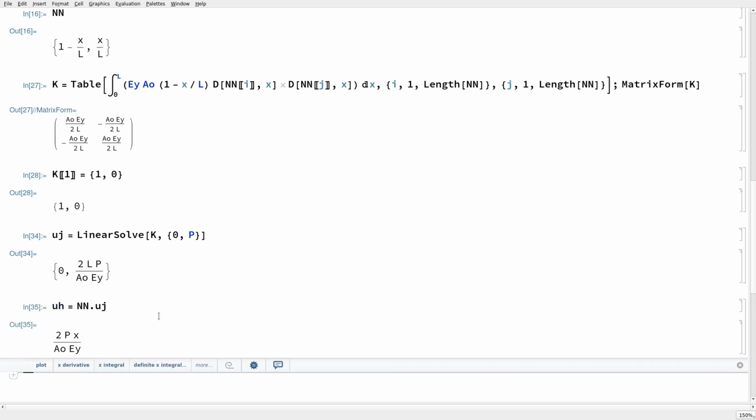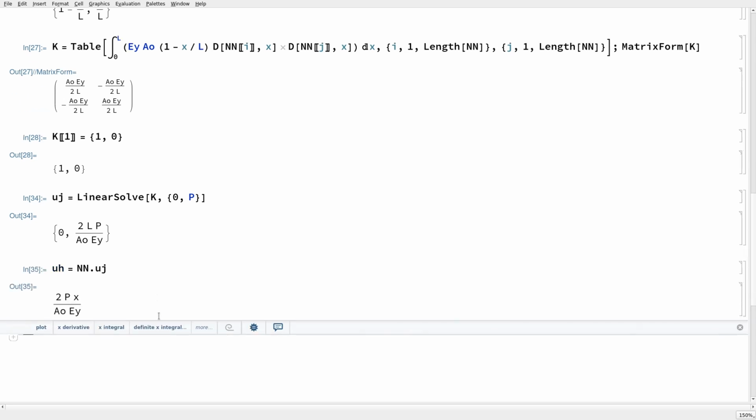So my full solution, right? This is a key difference between the finite element method, and finite volume and finite difference methods. In finite volume and finite difference methods, you discretize, and you all know at least a little bit about this if you've had reservoir simulation, right? In a finite volume method, everything in the cell is one value.